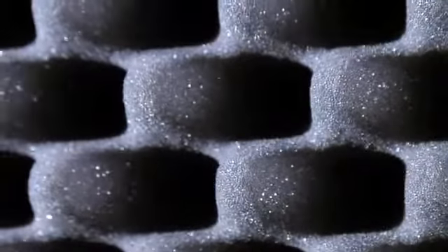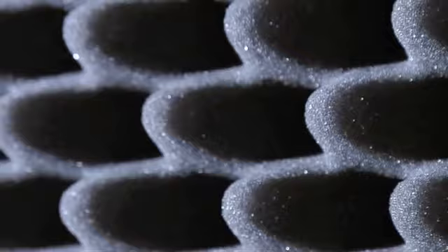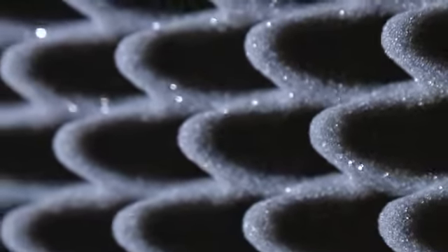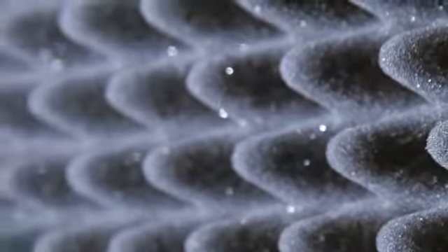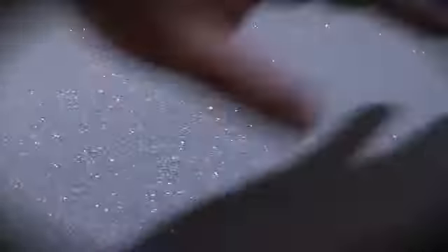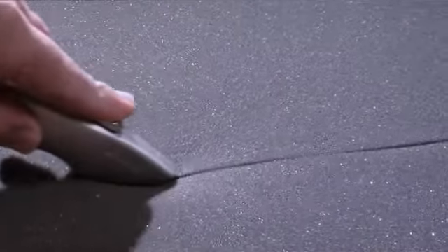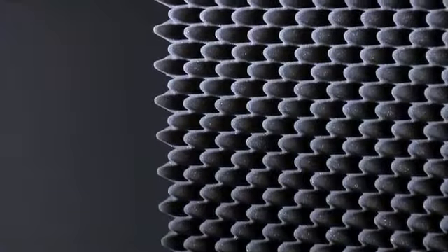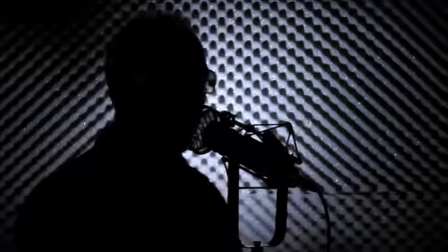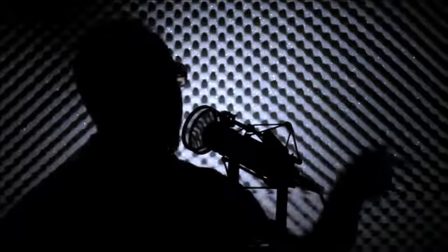For absorption, acoustical foam is designed to lessen or diminish the effects of echo and slap throughout a room, which are common problems in most rooms that weren't meant to be recording studios. Foam cuts easily with a sharp razor or knife and is pretty cost-effective for those working on a budget. Treating a room with foam will help to improve sounds you record with your microphone and also work well for monitoring your audio in a post-production environment.